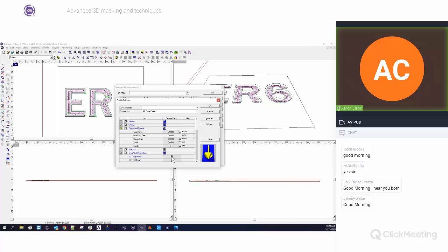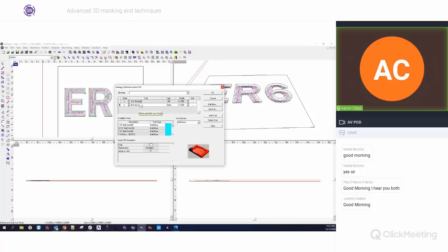This is basically what this little checkbox does: it essentially tells the island fill, hey, I want you to do a 3D engrave just like you were doing an engraved letter, but I want you to do it in the island fill. But the end mill allows me to hog out the center of the material so that I get a nice flat bottom to my letter. So I'm going to have a beveled edge and then a flat bottom down here.